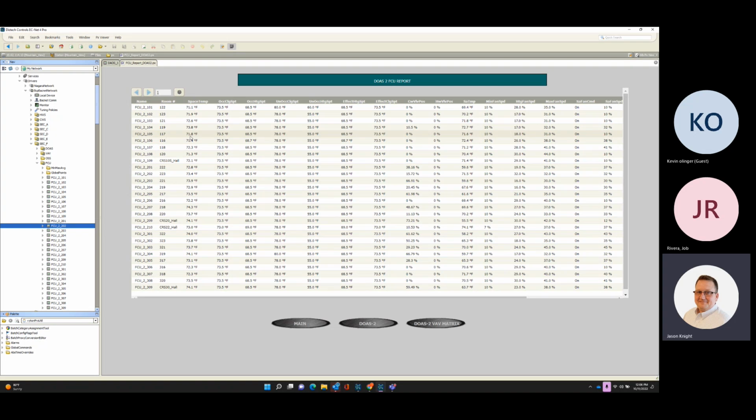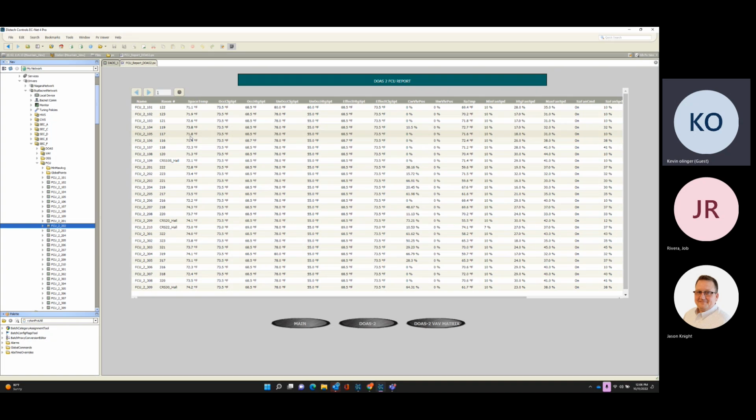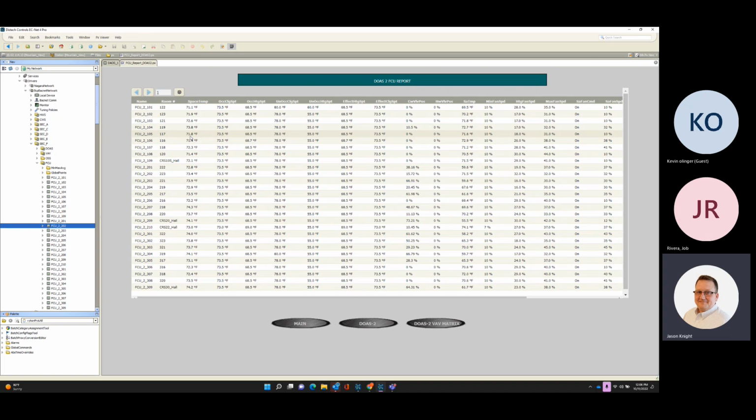Say, hey, man, it took an hour and a half to get up to set point, so we're going to start 2 hours prior. Or, it could be 15 minutes prior. It just all depends on each individual fan coil. So if one of those starts early, it's going to kick the DOAS on. Does that make sense? So the fan coil units can start independently with their optimal start routines. But yes, if any of them are called to run or called to occupy, the DOAS that serves all of them will fire off. Right.